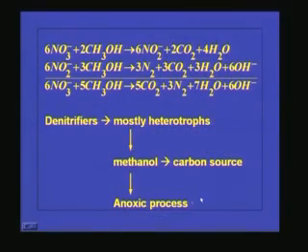So denitrification is an anaerobic respiration, that means in the absence of oxygen this denitrification takes place, or precisely we can call it an anoxic process. Inorganic compounds containing oxygen will act as the electron acceptor. So this is about denitrification.